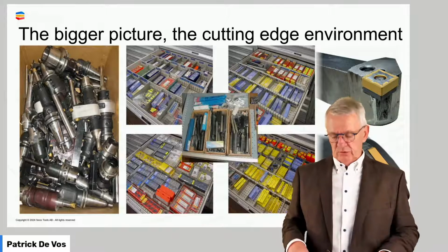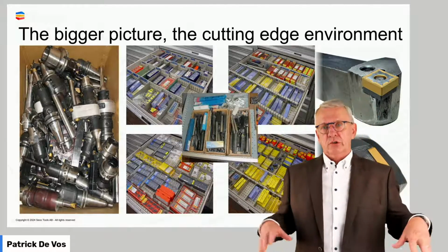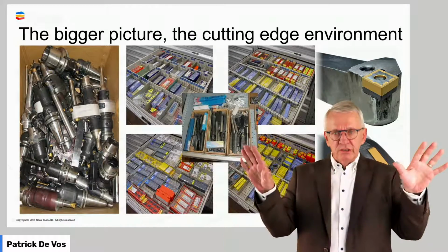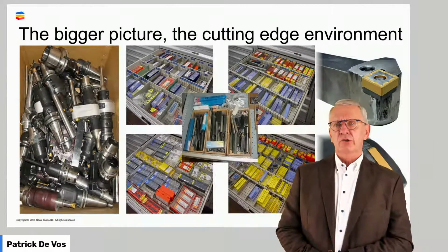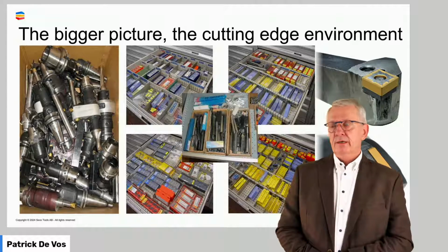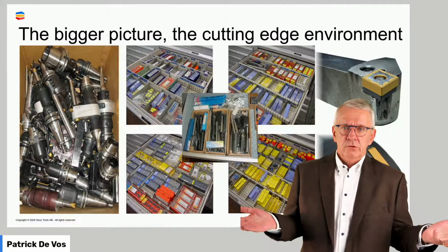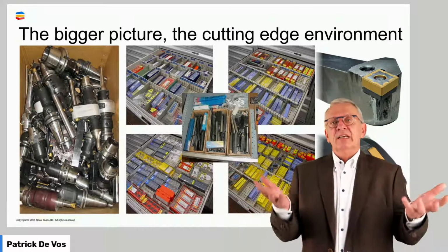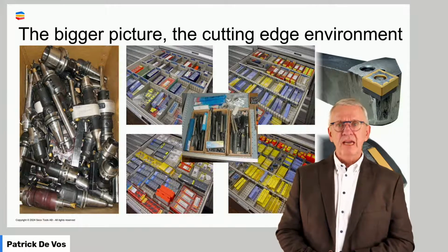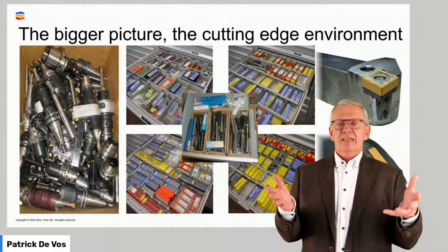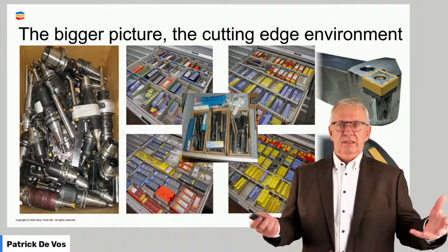And later on, I'm going to give you an example of what I mean. But if your tool holders, in the widest possible definition, are not in good shape, whatever your cutting edge is, it's not going to perform well either. So, step one, if you want to manage tool deterioration, is make sure your tools are in good condition. That's the start.